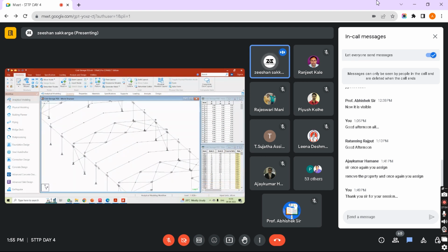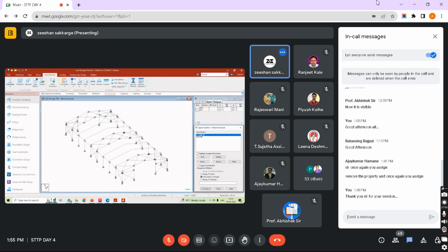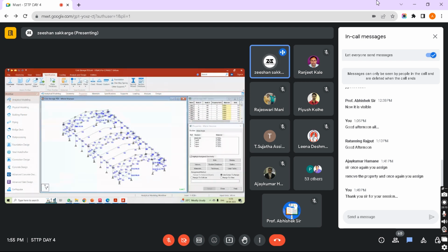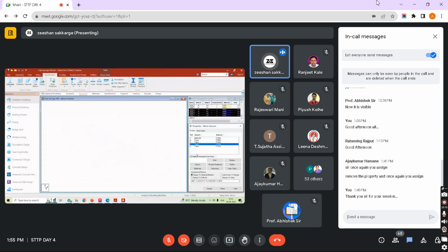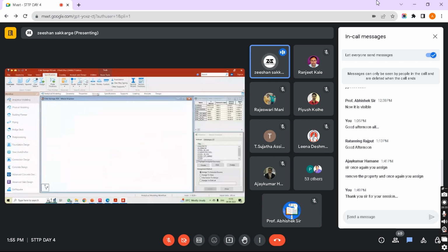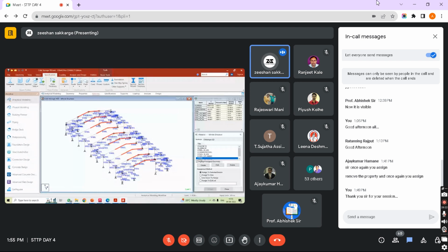For my bracings, I had given releases. That is where we use this specification. You can see this blue part, specifications. That is where we need it. In my previous model, we didn't use it. Geometry is what we prepare. Properties are the properties for various members. For the bracings, I used ISMC 150. Then for the tapered section, we had different properties like we have in our comparison. Material, of course, was steel.